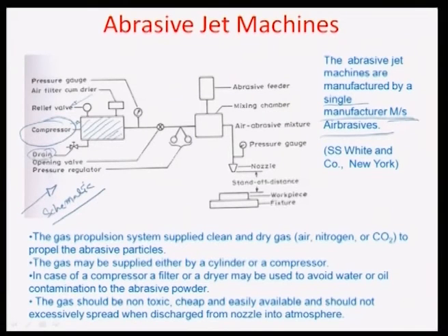And then of course, there are some other aspects like the air filter cum dryer, which is used for circulating the air into the chamber for cleaning it, and then once this compressed air is stored in this particular tank here, you can monitor the pressure by a gauge which is fitted towards the end of this compressor tank.